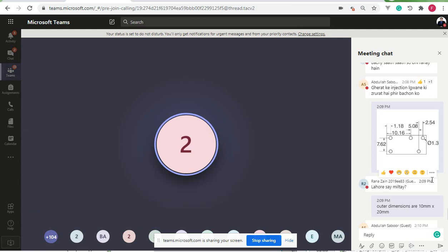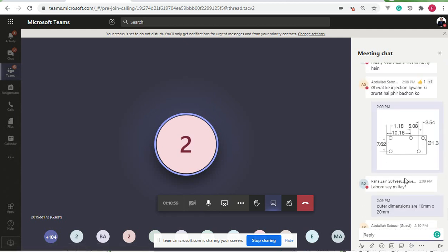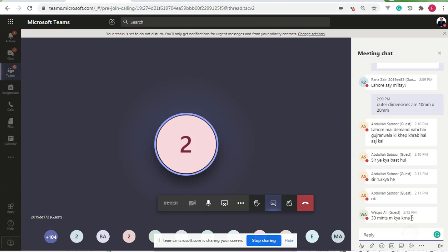This is again a relay. The two coils are on the extreme left, two pins over here. The remaining three are the pins of the normally open, normally closed, and the common points. And then the outer dimensions are approximately 20 mm cross 10 mm. So I hope everyone can see this one. The outer dimensions are 20 mm cross 10 mm, and you have to do this.